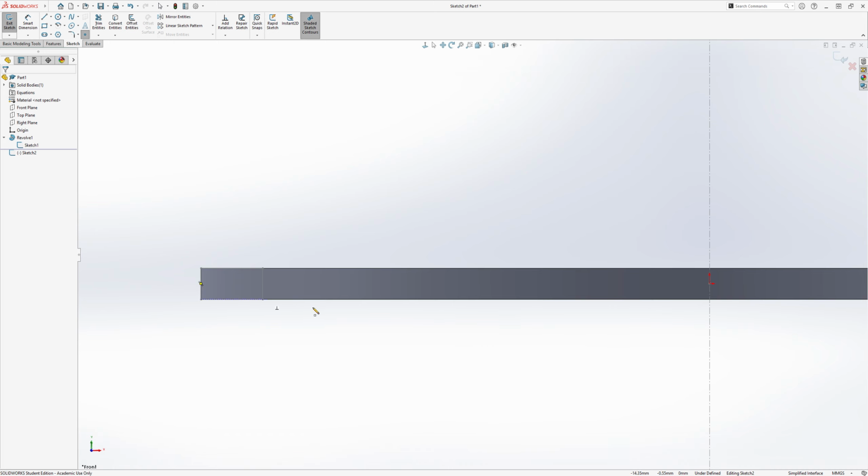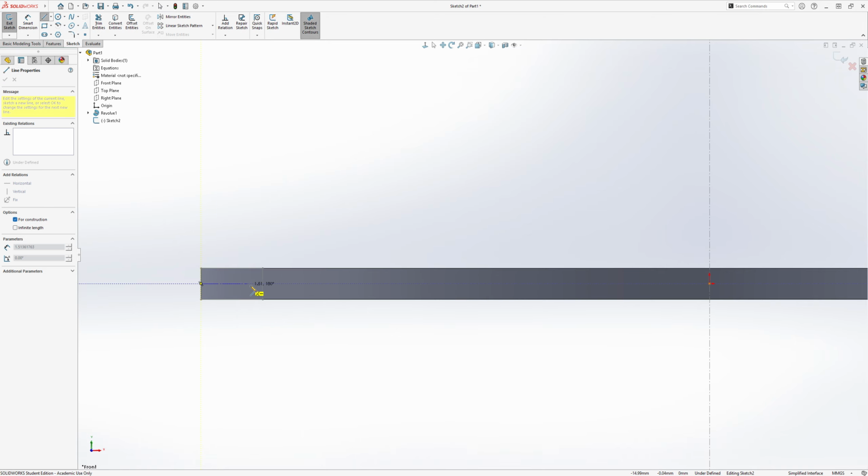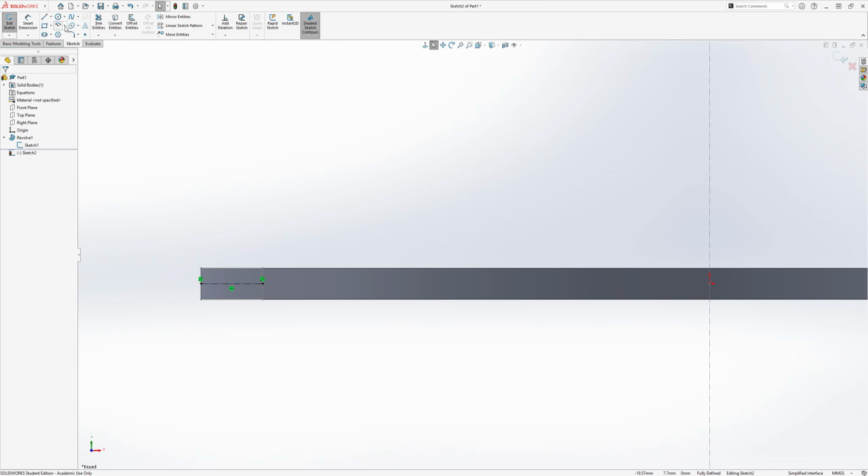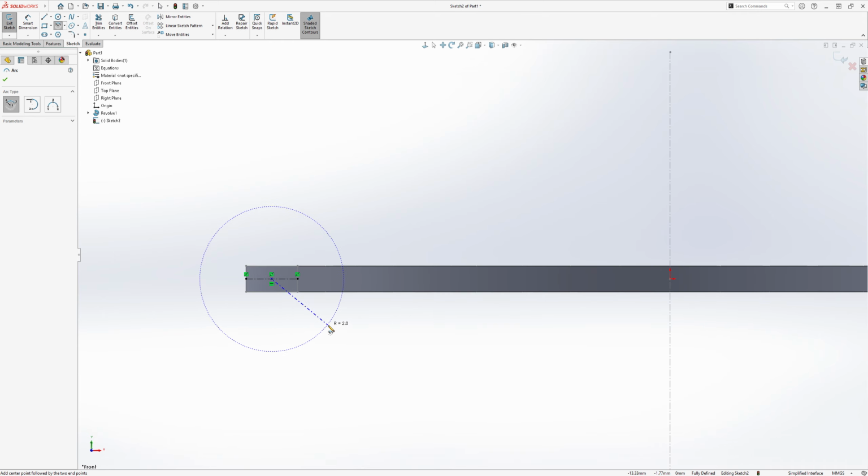See, the sphere that we're creating should be centered with this rectangle, in the center of the rectangle. I guess I'll just draw a construction line to find that center. So I'll draw a line like this. That'll be my construction line. And I'll just add a point for its midpoint so I can easily locate it. Okay, so from here, let's draw the center point arc. Here you go.